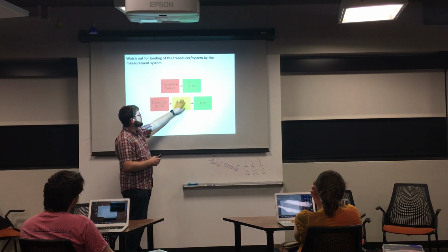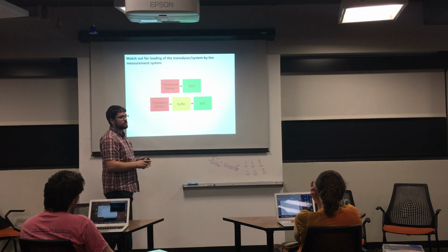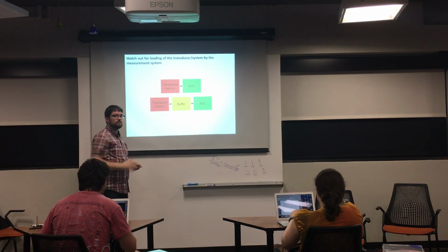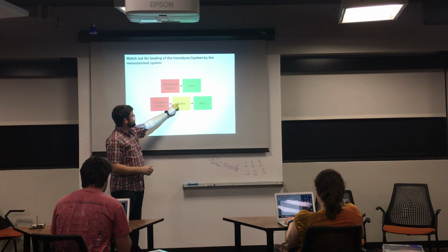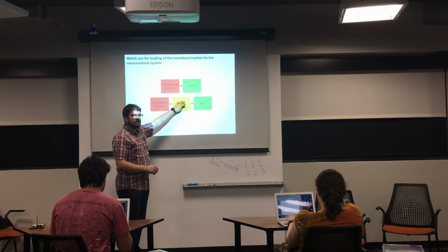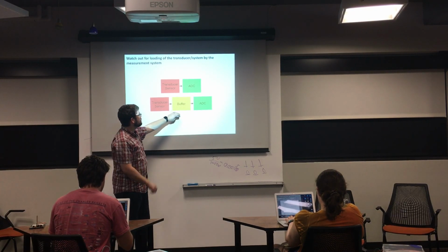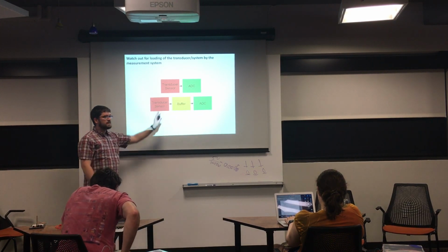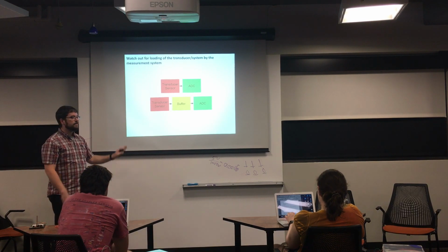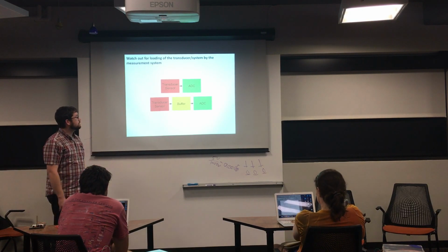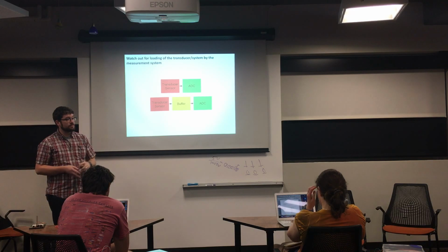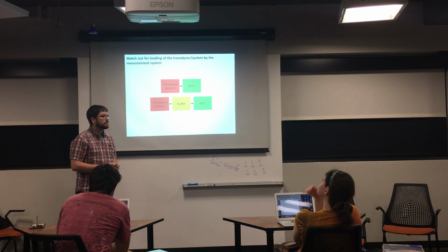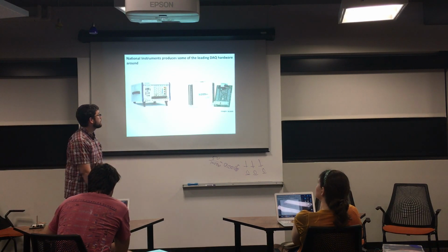To get around that, we put what's called a buffer in the middle. Buffer does exactly what it sounds like. It takes the transducer or sensor, it provides a high input impedance place for the transducer to go. And we even amplify the signal in here a lot of the time, though we don't have to. It'd just be a one-to-one buffer. And then it outputs something that the ADC can load down, and it's fine. It's going to make sure that it's always at the correct voltage. You're going to make buffers or buffer amplifiers a little bit later, once we actually have a chance to go over operational amplifiers and how to use them.